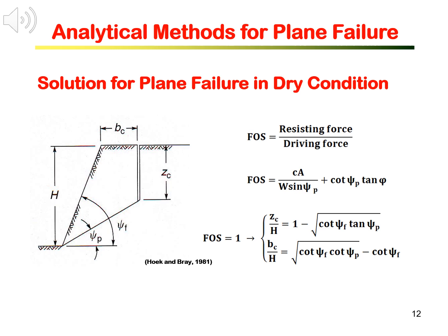Again, we need to formulate analytical solutions to calculate the sliding driving force and the sliding resisting force in the plane sliding direction. And from there, calculate the factor of safety. Again, a factor of safety less than 1 is an unstable slope.